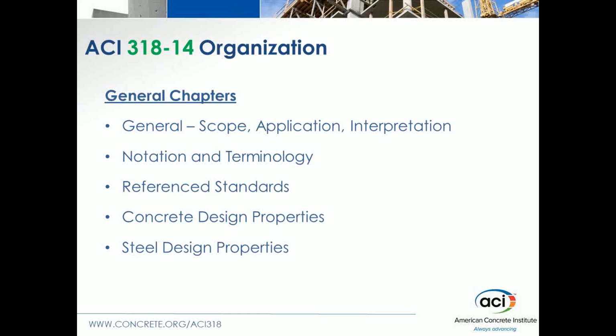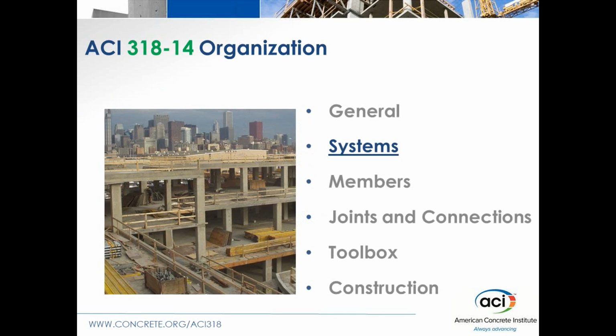Generally, grade 60 ASTM, but there are certain types of steel, for example, in seismic applications where, because of ductility requirements, you have to use a different type of steel. So these are the parameters that the licensed design professional may need in order to start their design.